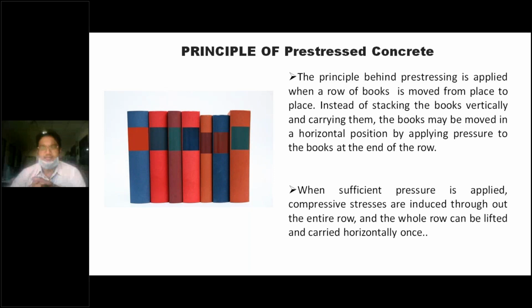That is exactly the pre-stressing technology which we use in structural elements, particularly beams, girders, even slabs and all. Here also it is the same. When you pull the strands, you are applying compression forces in the beam, so the beam will try to lift up. When it lifts, it goes into hogging, isn't it? Hogging is nothing but the contraction of the sagging of the beam based on its loading condition, right? So this is the principle of pre-stressed concrete or pre-stressing technology.